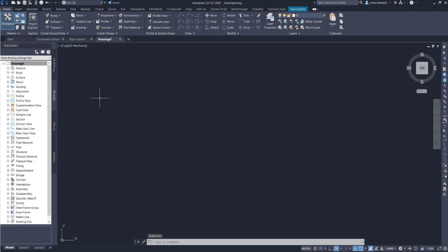Now, a starting point for most InfoDrainage models is going to be some surface data. We don't strictly need it, but it's useful for defining things like manhole cover levels, and when objects such as ponds flood onto a catchment surface, we need it for routing the flood water across the catchment surface. So it's used for a variety of different items. We can use it to set the level of a pond perimeter, for example. A good ground model or some good surface data is really the cornerstone to a good model. So the first thing we're going to bring in is that surface data.